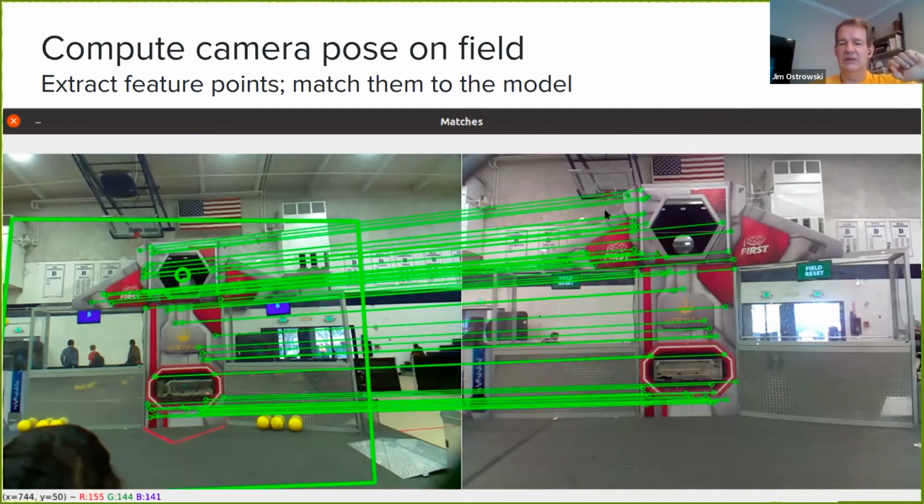So, just to give an example, let me find a good one that's easy to reference. Maybe start at the top left. We detected this point up here in the top left. Based on all the things we did to begin with, our homography says that point in space is 8 meters from the center of the field, a meter into the field, and whatever it is, 2.5, 3 meters high in the Z direction.